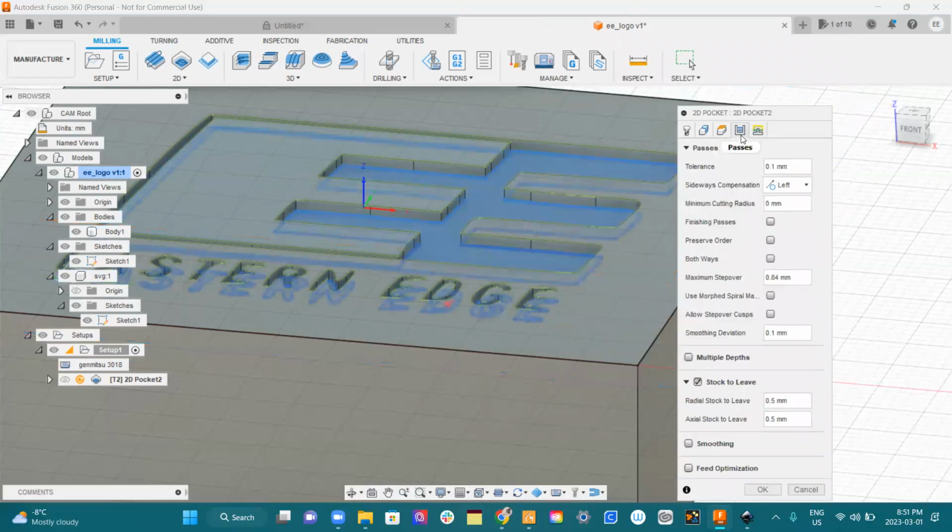Passes. So this is not a very robust machine. I could tell it to try to drill down an inch and then go sideways. Well, first of all, it's not even an inch thick, right? So how much material do I want to remove each time it goes around? Because it's going to cut this really thin, and then it's going to go around and cut it again and again and again, spiraling down until it hits the bottom of it. So I want my passes to be 0.1 of a millimeter. So this is like 10.